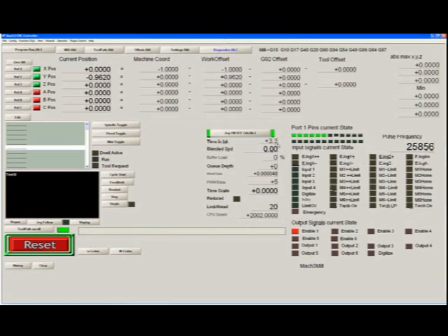That's a fairly good number and indicates a fairly low load on the system. The actual load on the system would be 25,856 multiplied by 3.5 microseconds, which would be equal to about 90 milliseconds per second. So that's about an 11% load on your system, which is not too bad.